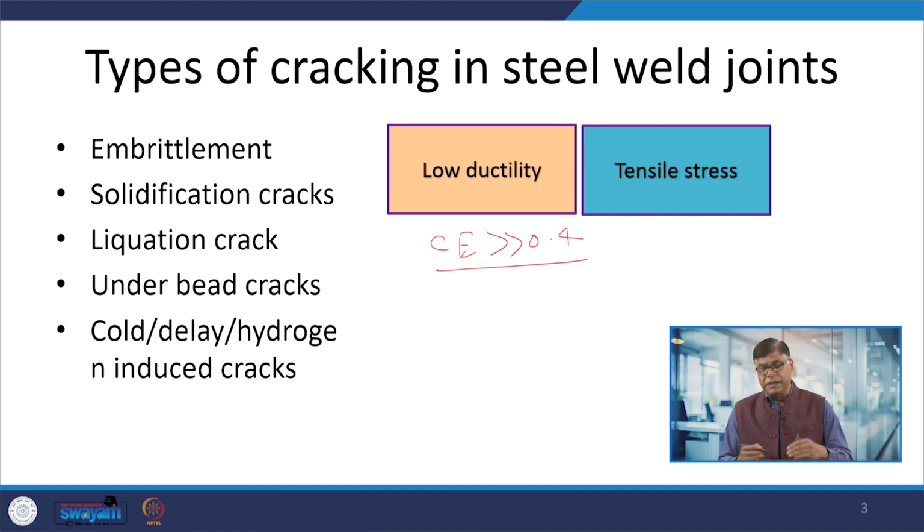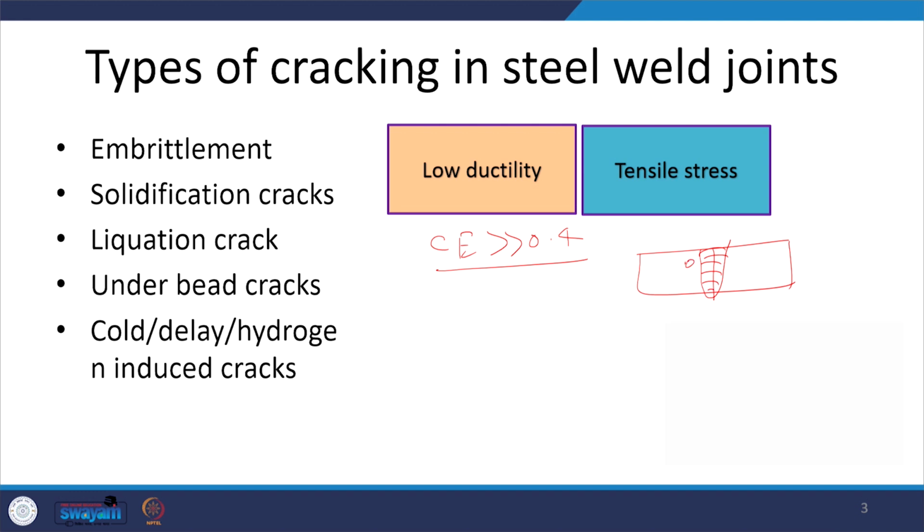During the welding, obviously the edges will be brought to the molten state, but the zones next to the fusion boundary will also experience high temperature, and the phases next to the fusion boundary will form austenite. Farther away this transformation may be partial, like pearlite transformed into austenite, or ferrite and pearlite both transformed into austenite.